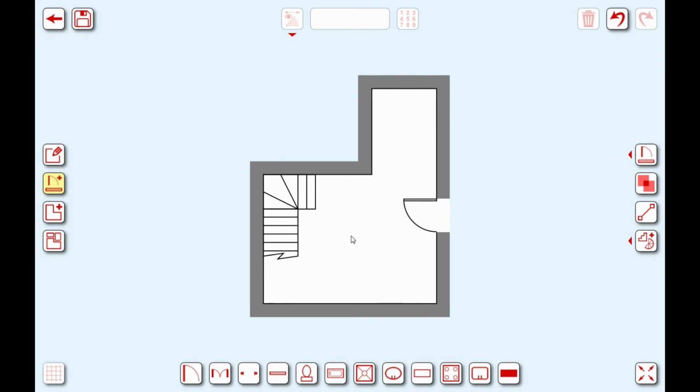So we're now going to look at adding blocks to a plan, and there are two different types of blocks: square rectangular blocks and triangular blocks. Now we can add these and move them anywhere we like within the plan, and we can use these to show areas such as pipe boxes, etc. So we can move this in free space, or we can drag it into, for example, a corner or onto a wall, and it will snap.